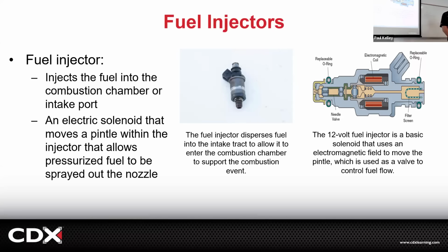That does happen. That's what the filter screen is. But if the fuel makes it past there, it goes into this passage, right? And it goes down this passage. It's going to get stuck right here at a needle valve, or sometimes they'll call it a pintle, right? So that fuel injector won't pass fuel. Make sense? It's sealed. It's almost like a V is the seat, and the needle seals against the seat, and the fuel's there.